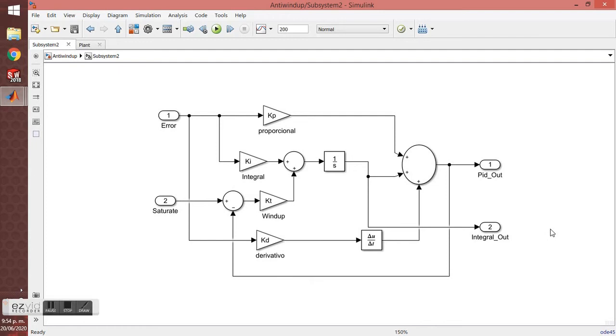Anti-windup control technique. For a control system with a wide range of operating conditions, it can happen that the control variable reaches the predetermined limits of the actuator. When this happens, the feedback loop remains at its limit regardless of process output, whether you use a controller with integral action. The error will continue to be integrated, further increasing its value. This means that the integral term can become very large, and this is the effect called windup.